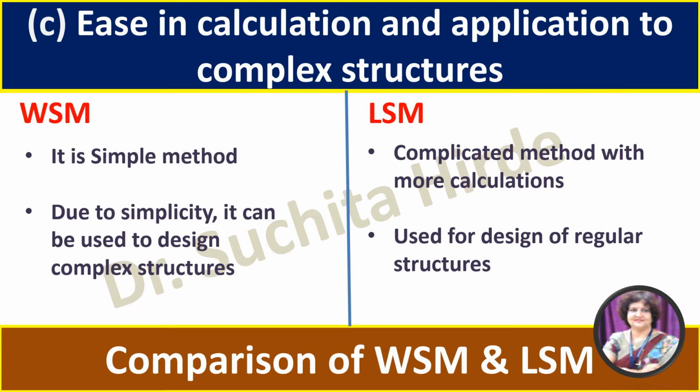Now limit state method is adopted by our IS code for all types of structures. Since when we design our structure using limit state method, it satisfies the collapse condition as well as the serviceability condition. So the structure designed by limit state method is economical as well as serviceable.